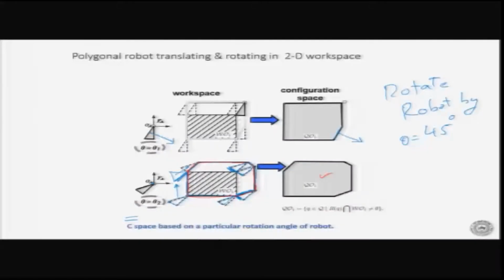And now, if you want to write a program which can automatically do this, that means I am giving you the vertices of the obstacle, you have to find out the C space obstacle. Okay, what is the logical way of doing it? Now, as in the previous case, which is shown on top, it is very clear that there was only one inclination here. The other faces are perpendicular to the x and y axis, so it does not cause any angle. So, if I take a vector which is perpendicular to this surface, then this vector appears here, and this is my line corresponding to this side. That is very clear. Now, what about this one?